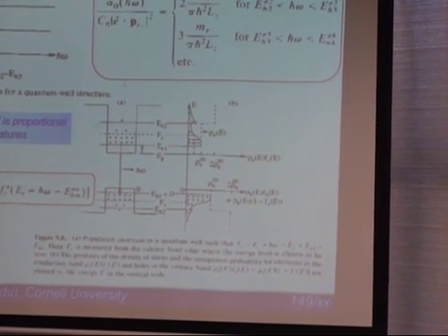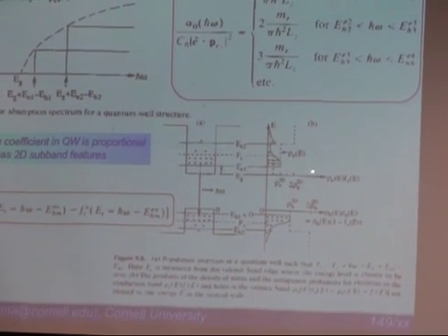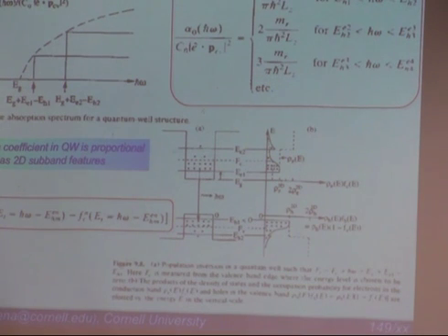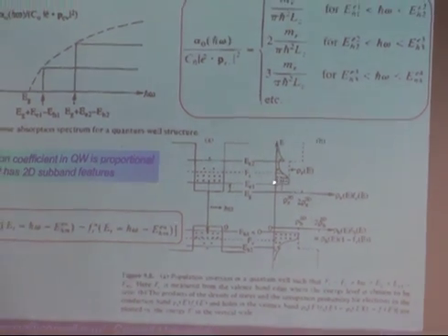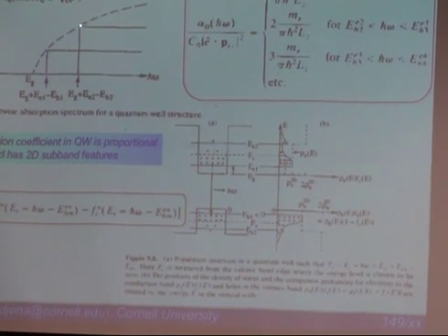Remember the Fermi function is basically 1 far below, and then it goes to 0 gradually here. Does that make sense? And the density of states is constant, so this is kind of the tail of the Fermi function, but suddenly there's a discrete jump because the second subband just kicked in, right? Therefore, the Fermi function is still going down, but the DOS has suddenly doubled or something like that. So you have this little notch here. So the carrier density looks like that. Does that make sense, what we are sketching here?